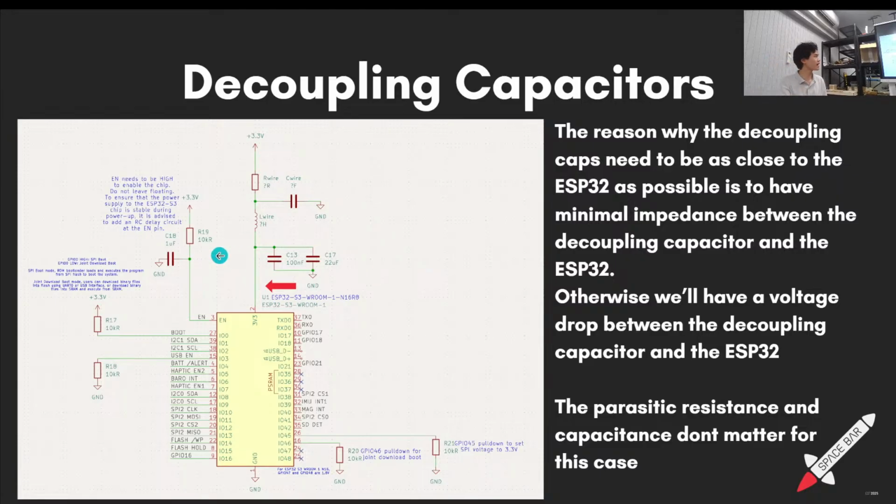So I've got this tiny decoupling capacitor close to the chip for small fast current draws, and I've got a huge bulk decoupling capacitor which is bigger, and that's for bigger versions of the same event basically. Okay, and that's usually placed a bit further away just because it doesn't need to be so close and it doesn't matter. Or because I didn't have space on the PCB. Fair enough? So some microcontrollers will have 6 power input pins.